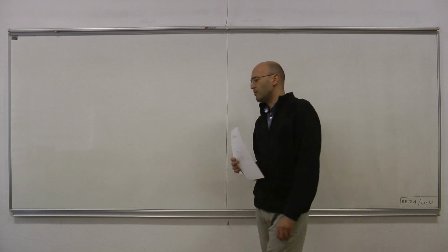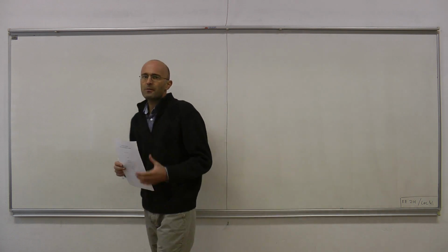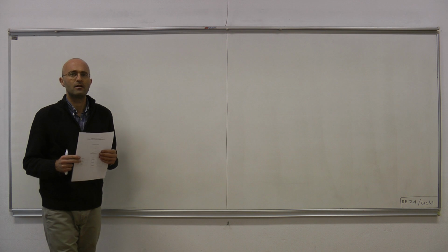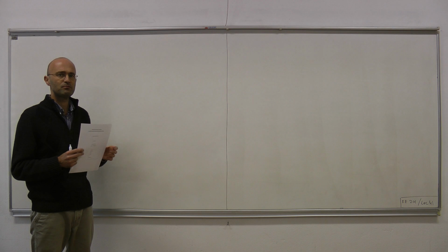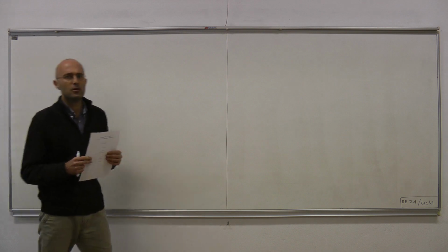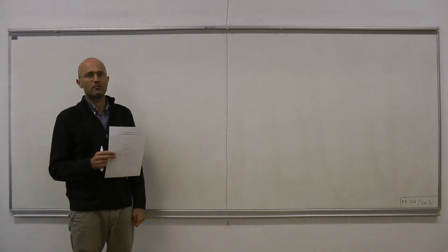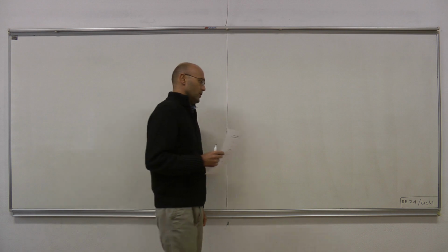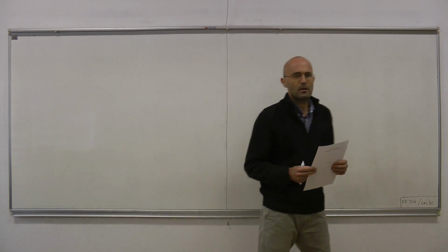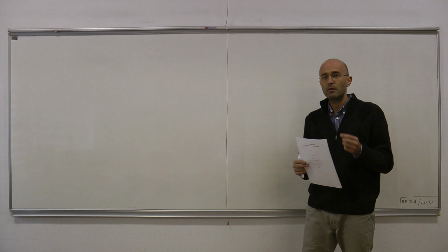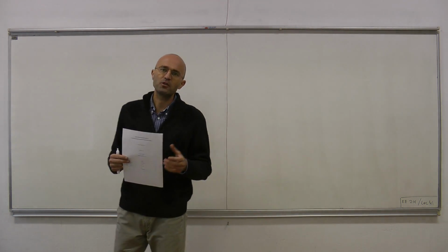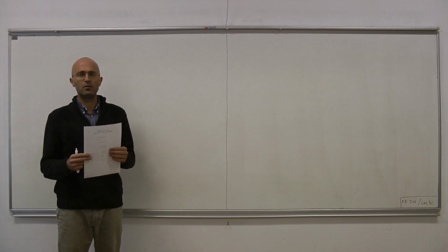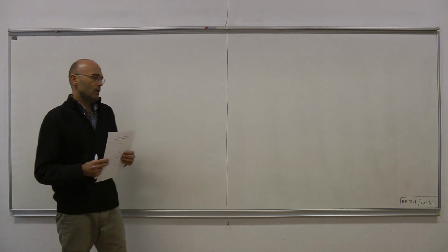Now, the impulse response is defined in the same fashion, the only difference being that from the input, you apply a unit impulse waveform. One nice thing about impulse response is that if you know the impulse response of a circuit, then you can figure out the response to an arbitrary input.